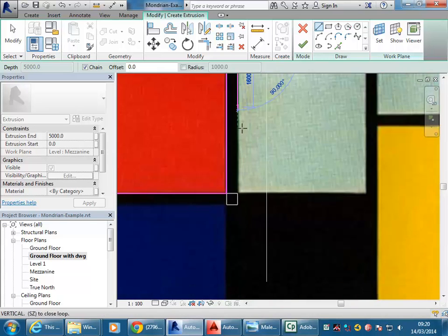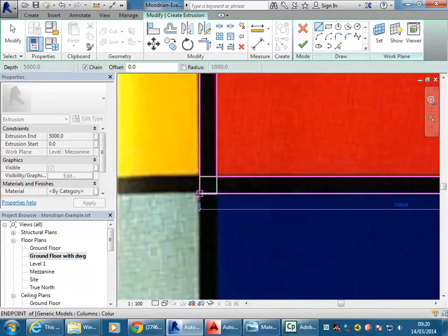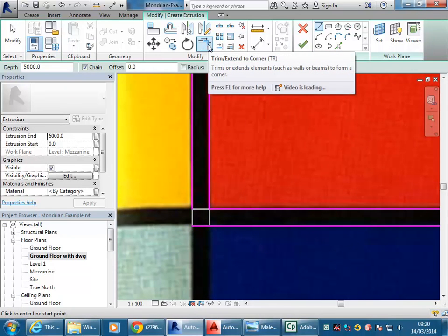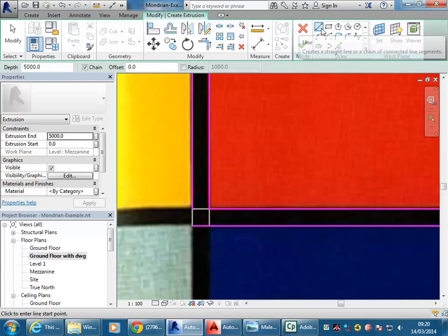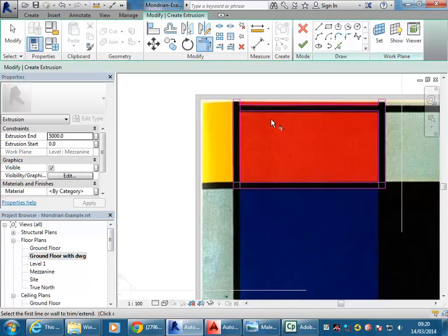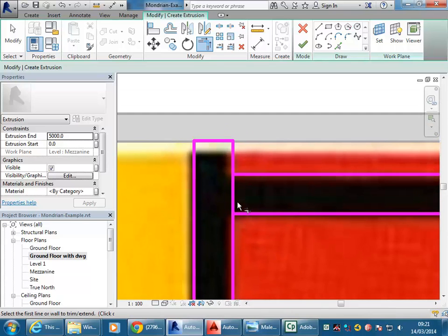But with the inside part here, yeah, so I've just drawn lines, and hopefully with the line tool you get a lot of practice with that. But if you haven't used the trim tool very much, I'm just using that to join those two lines at the corner to make sure it's closed. It works just like fillet with zero radius and all that. And so it is the main trim tool though.